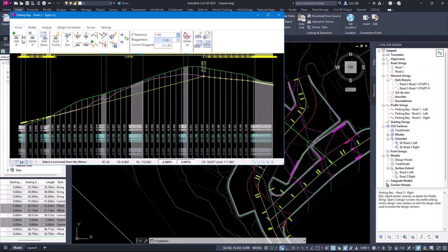Snapping reference. Most people probably still work on the concept that that only works on the surveyed surface or the natural, but it's not. It's any design constraint you make becomes a snapping reference. And I know Jonathan made this comment last week, and I'm going to make it again. So you can add design constraints in, and then snap to them, which is exactly what I want to do for this exercise.